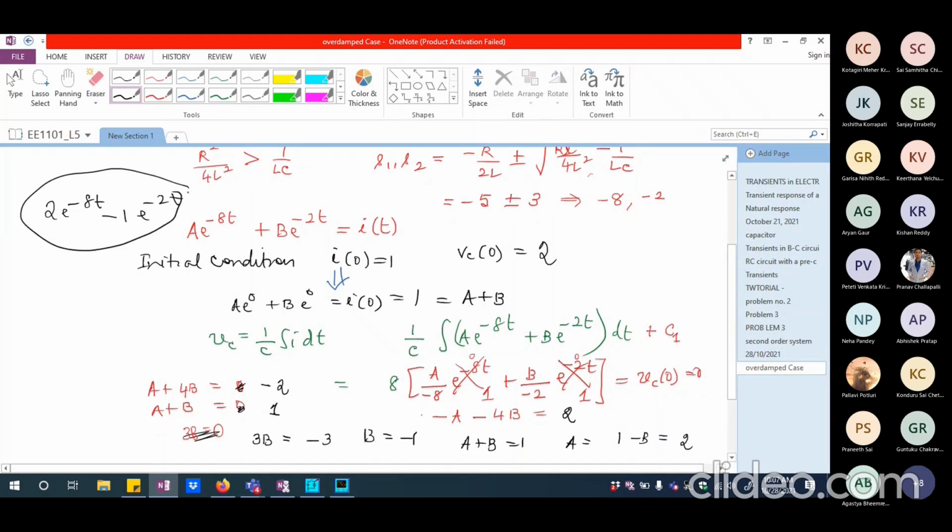So this comes out to be all right. In which case, see, probably we are negating the condition itself. The initial equation when we write V, which is 14 volts, equal to Ri plus L di by dt plus 1 by C integral I dt with an initial value of capacitor voltage also.